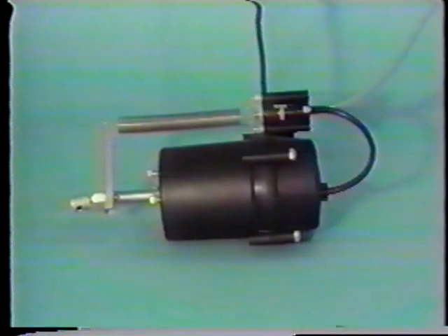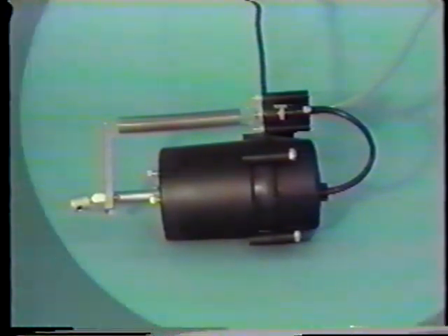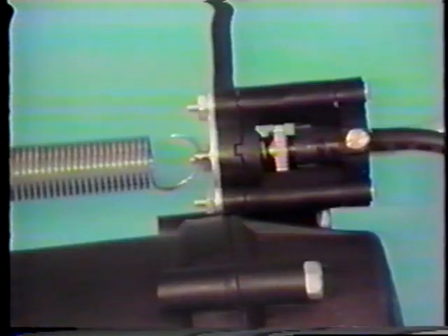Here is a 3-inch actuator, the 2473 series, with a positive positioner attached to it. A positive positioner is used to properly sequence single, or in some cases, multiple damper actuators within the control sequence. The positioner is used where the position of the damper is critical to system operation.